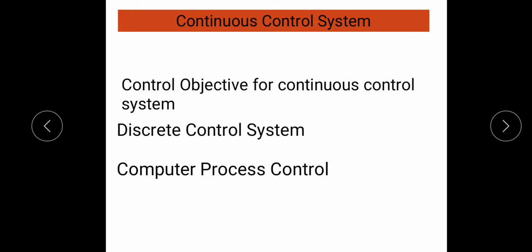Coming to feedforward control, the second objective, the objective is to anticipate the effect of disturbances on the system and to compensate for them before they can occur. Corrective action takes place as the process is ongoing by corrections of variables that act as new inputs into the system.